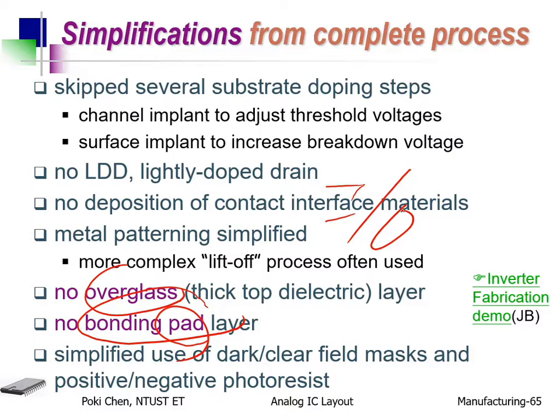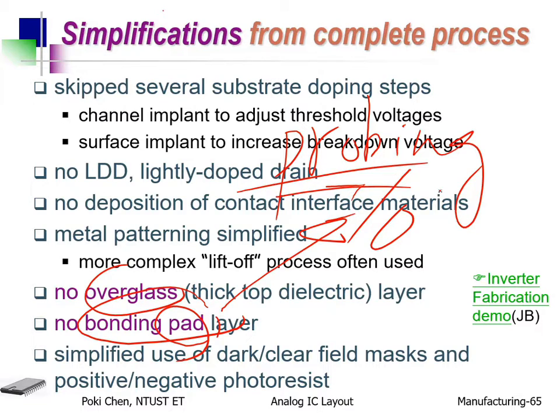We have two kinds of pads. One is for I/O, for input, to get the input-output signal, and the other to be connected to the outside world. And then we have something called probing pads. For what? For testing only. After fabrication, we need to make sure nothing goes wrong. But how? We need to measure it, right? How to measure it? The chip still needs to be contacted. So we need such kind of probing pad.